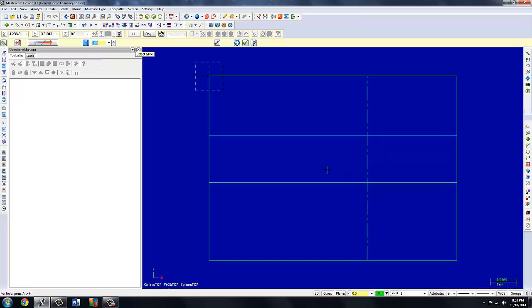I also have a dimension of 0.5 that depicts the intersection of the slant that's coming in, that angled line. I'm going to put that one in as well. Accept that. Put in 0.5. The 0.5 is off of here as it's dimensioned. I'm going to accept that one. And then I've got some vertical lines to put in as well that will handle intersections off of some of the angled lines in that area.